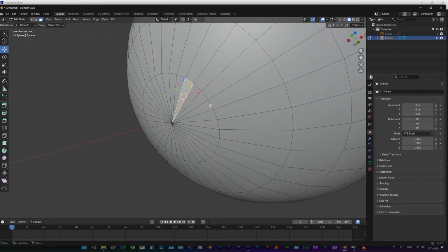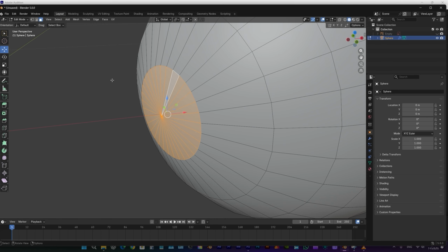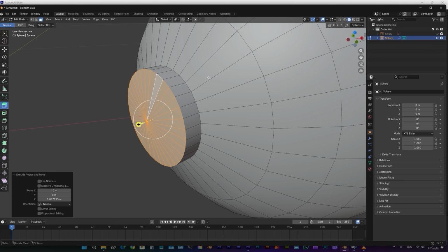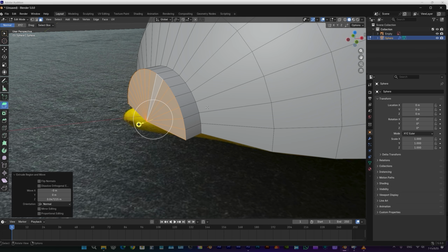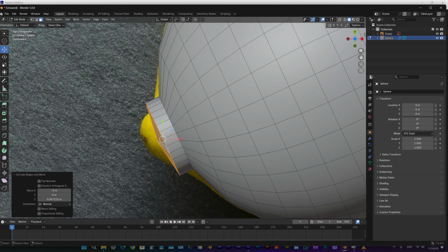We'll hide the drawing for now so I can see all of this clearly, because I want to select all these faces. Okay. After selecting it, we have a very cool tool here that I love to use, which is the extrude tool. When I select it and click the plus sign, it extrudes outward, right? Let's bring back the reference image to see how far we need to extrude and go back to the Z-axis.